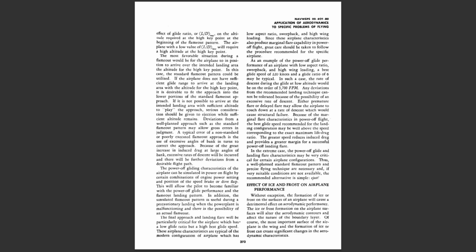The final approach and landing flare will be particularly critical for the airplane which has a low glide ratio, but a high best glide speed. These airplane characteristics are typical of the modern configuration of airplane which has low aspect ratio, sweepback, and high wing loading. Since these airplane characteristics also produce marginal flare capability in power-off flight, great care should be taken to follow the procedure recommended for the specific airplane.